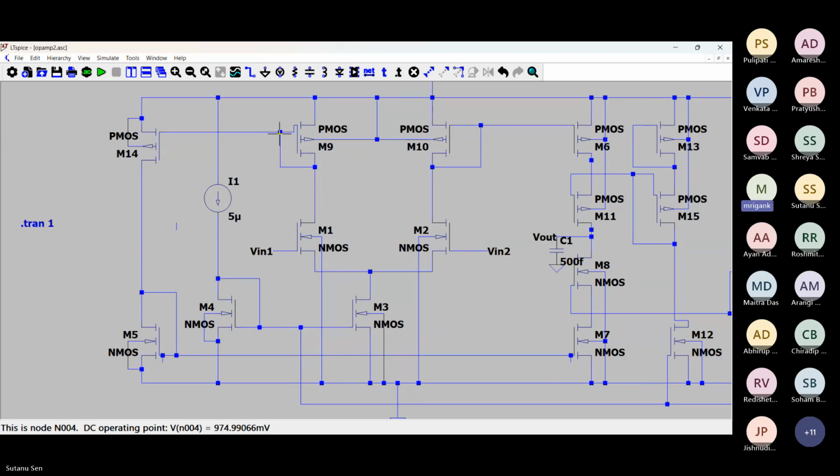There is some problem in the model somehow, because the small signal currents are coming similar. DC current in the two outputs, the left hand side and right hand side, second stage is also similar, but somehow from the DC point of view there is a difference. So M6 current, M14 current is also same. DC current is same, right? M6 and M14. Yes, sir. They are same. So despite difference in the VSG, the DC current is same. That may be because again this side has a different kind of channel length modulation. But I think there is some problem.